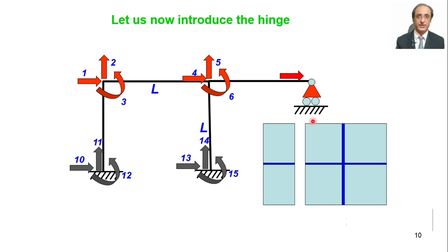So we do a modified numbering. We first number the rotation here, and number the degree of freedom associated with the vertical reaction in the end, so that we can club it with the reactions. That's how we have adjusted the numbering at this joint. This is essential so that we don't mix the load terms with the reaction terms. Otherwise we will not be able to do this kind of partitioning and we will not be able to solve if the two are mixed together.